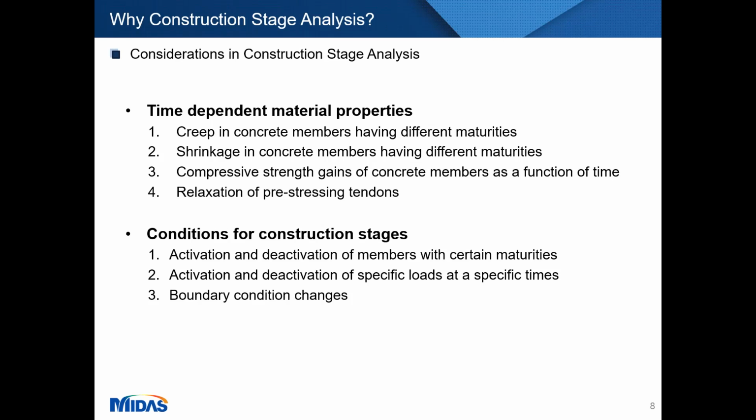Construction stage analysis is needed for statically indeterminate bridge structures, and the different considerations that we need to make are: one, the time dependent material properties. So here we need to consider creep in concrete members, then we need to consider shrinkage, compressive strength, and relaxation of a pre-stressing tendon.